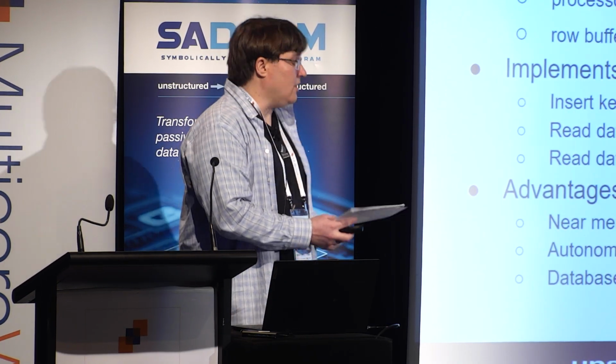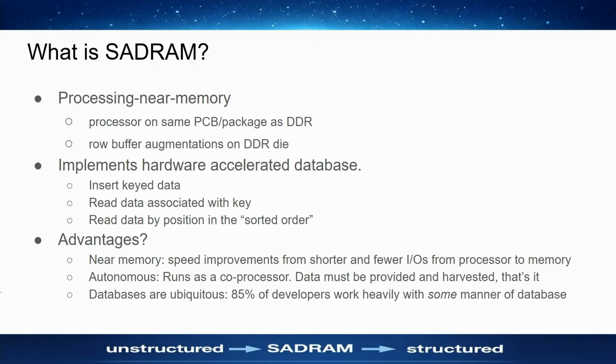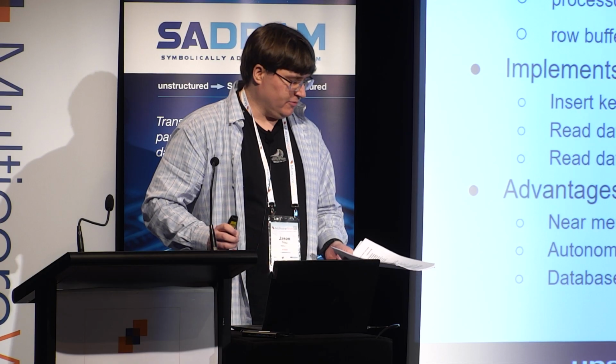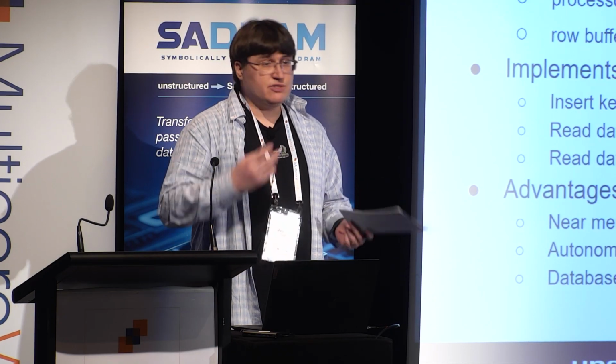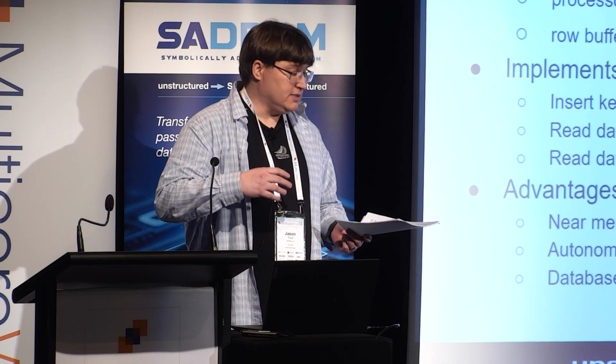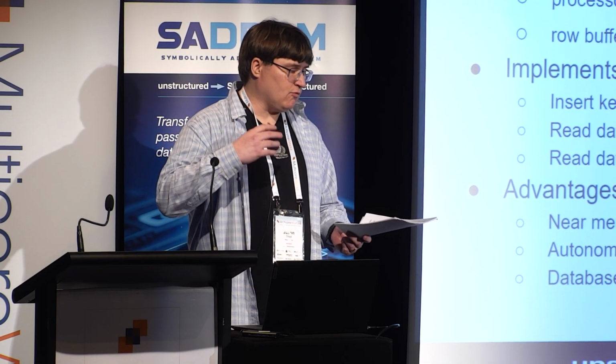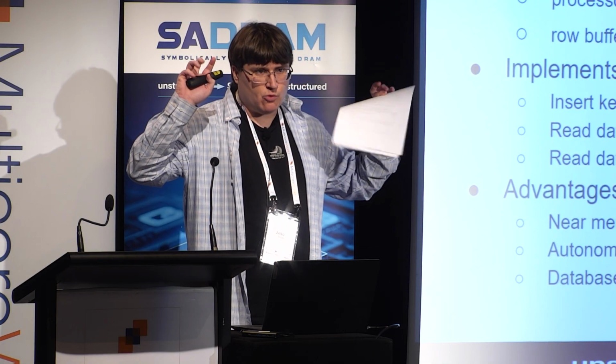All right, so what is SADRAM? Zoomed all the way out, SADRAM is an augmented processing near memory architecture, which augments DRAM by putting an autonomous database next to DRAM chips and within DRAM chips. Now, you can add record data associated with a key. You can delete data, and you can read data in the quote-unquote sorted order.